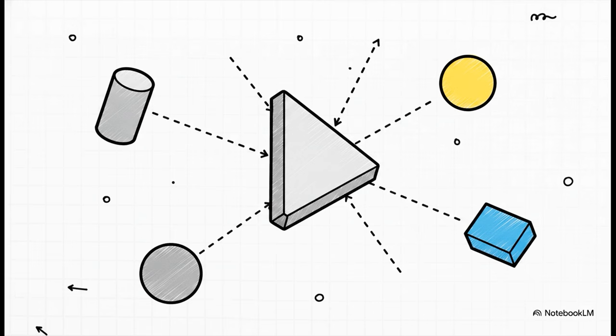We're going to zoom straight into the ultimate anchor of any drawing, the datum reference frame. Specifically, datum features A, B, and C. Everything, and I mean literally every single geometric tolerance on a print, every intricate little control branches directly from these three letters. They are the absolute foundation.